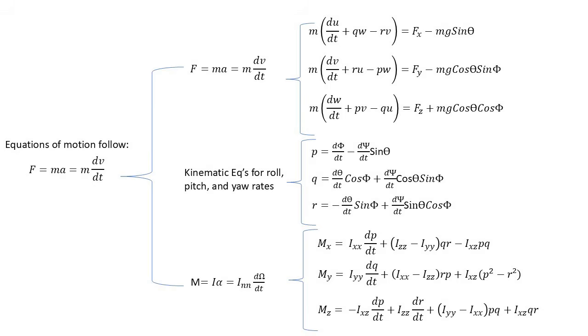To quickly review static stability from aerodynamic first principles, we can evaluate the aircraft motion by isolating the moments about each axis independently. Doing this yields lateral directional, or roll-yaw stability, and longitudinal stability, which is more critical and complex than lateral directional stability. If a wing is displaced from its equilibrium condition to a higher alpha, and therefore a higher CL if not near stall, it should return to a lower CL to be statically stable.